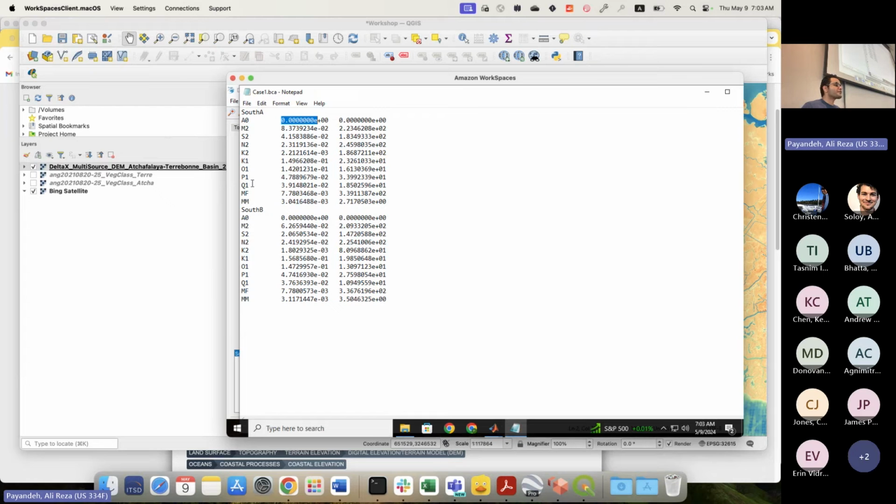Obviously, we don't need all of these tidal harmonics because we are located in Louisiana, northern Gulf of Mexico. Tides are diurnal. Just K1, O1, and M2 probably. These three explain 99% of water level variation. But no harm, we are going to use all of them now. So you see we have M2, S2, N2, K2, K1, O1, P1, Q1. Probably we could just use K1, O1, and also maybe M2, where is M2? Yeah, here, and delete others. But we are going to use all of them now.